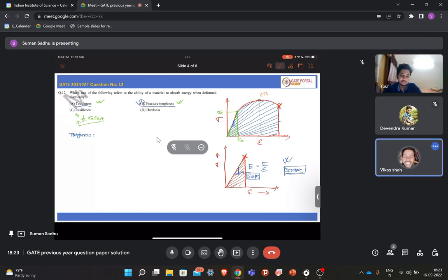Sir, toughness, as you already told, is maximum energy it can absorb in plastic region without failure, and fracture toughness is from the point it starts fracturing. But here also it is fracturing and this total energy we call toughness, right? But what is fracture toughness? Are these two things same or different? No, sir, different.